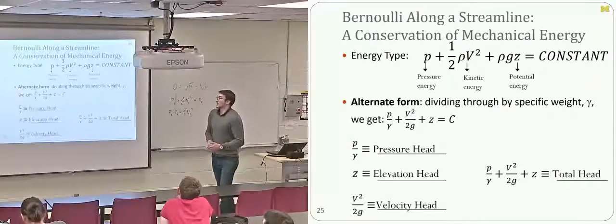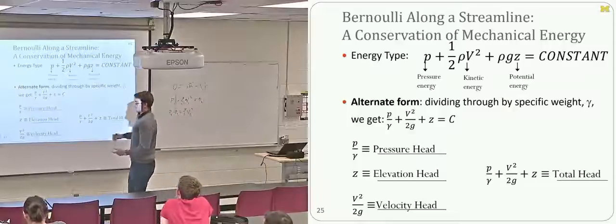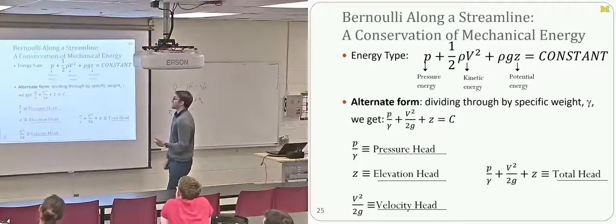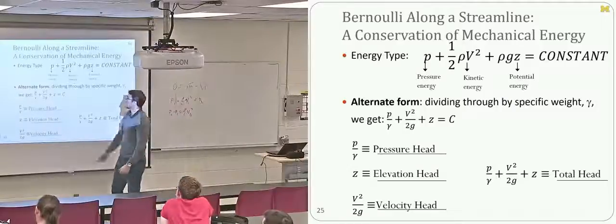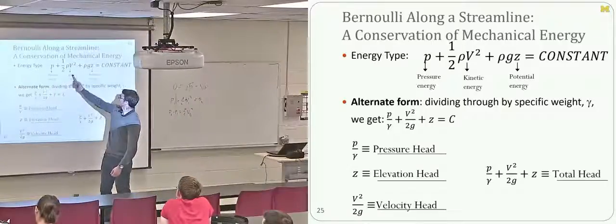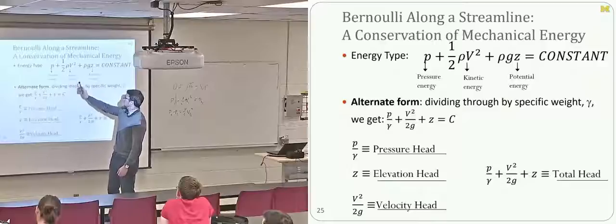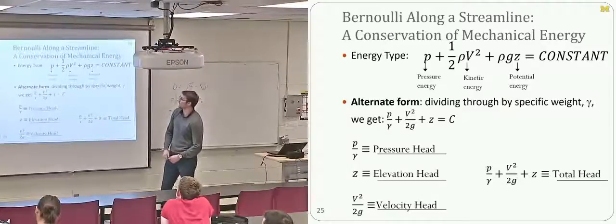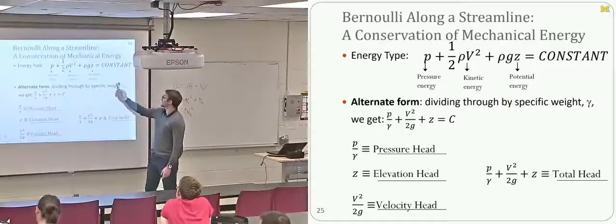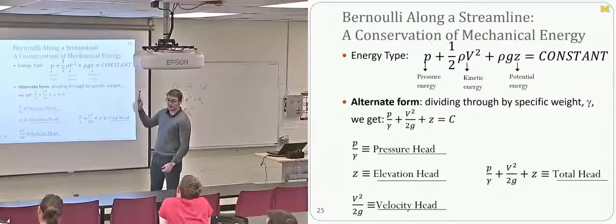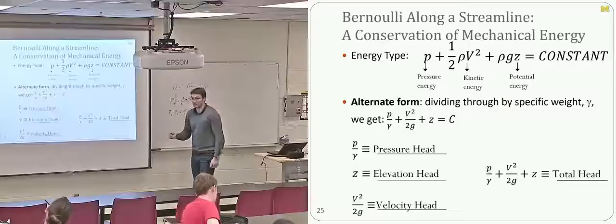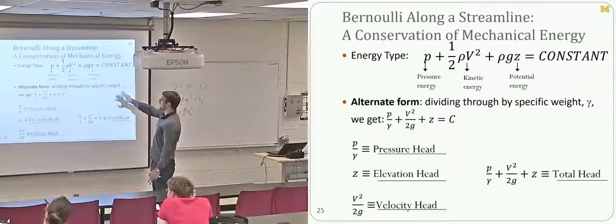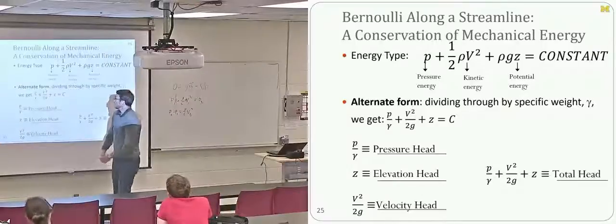So Bernoulli equation is, as I said, F equals ma along the streamline. It's also a way of expressing a conservation of energy, where P is your sort of potential energy, your pressure energy, rho v squared is your kinetic energy, and this is your gravitational potential energy, right? The idea is that the conservation of energy says that these have to be constant. All the forces here are conservative. Gravity and pressure don't cause any heat dissipation, and so we don't lose any energy to thermal losses.